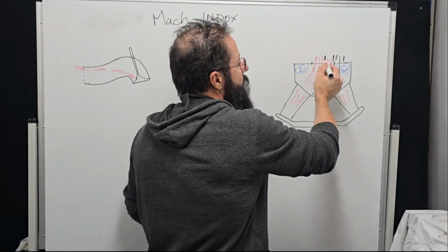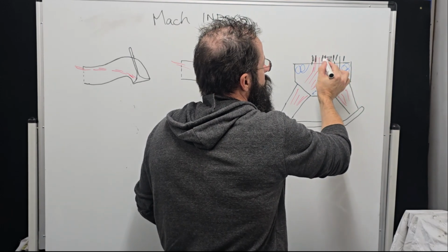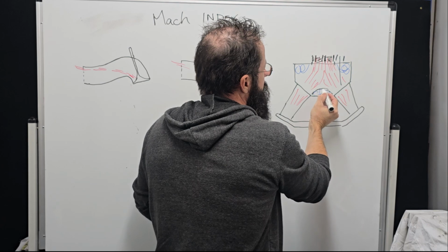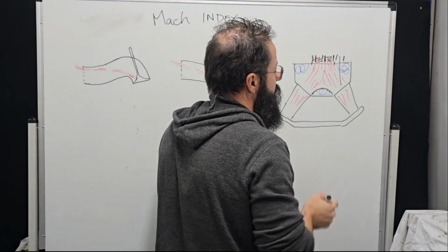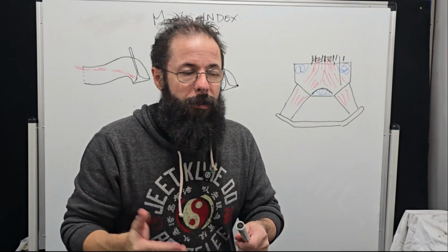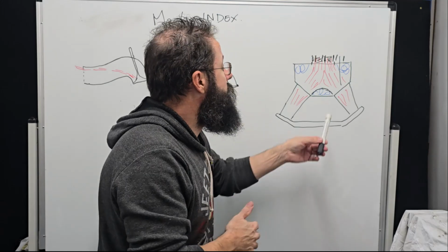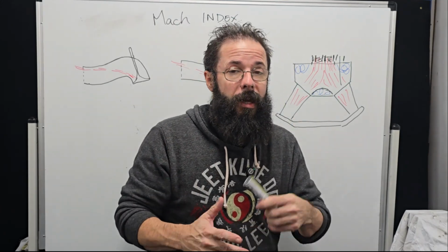But if you can't do that, so if we have something like this where we've got a bore there, what I tend to do is I build a dome in the floor. It helps in a couple of ways, but we're deleting a lot of that dead area that's only going to create turbulence, let fuel drop out of the air and so on.